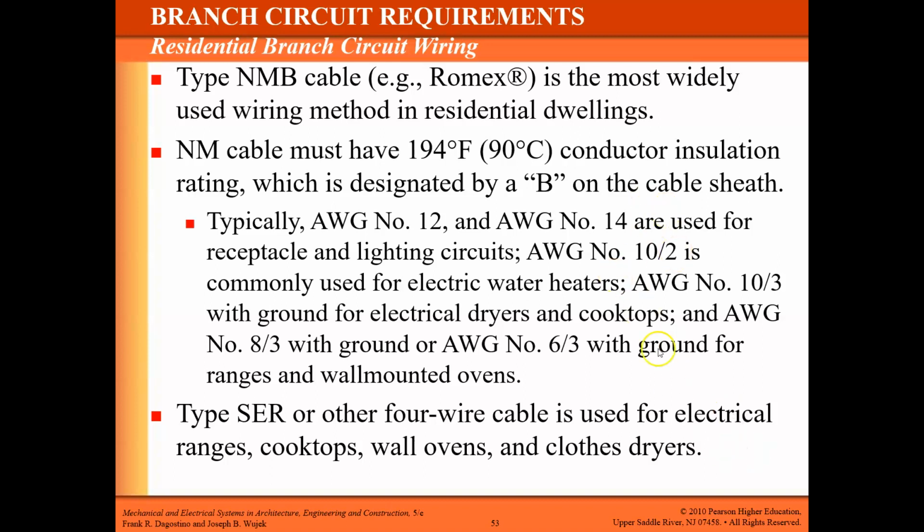So 10-2 would have 2 number 10 conductors plus probably a ground as well. So that little number doesn't include that unsheathed ground wire.